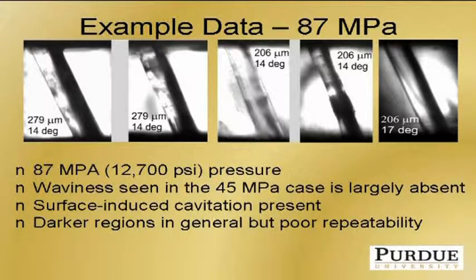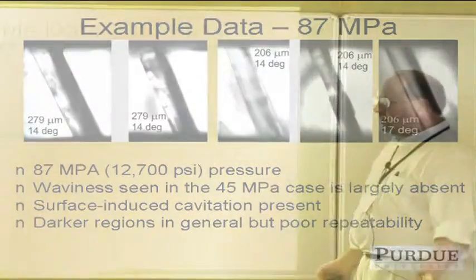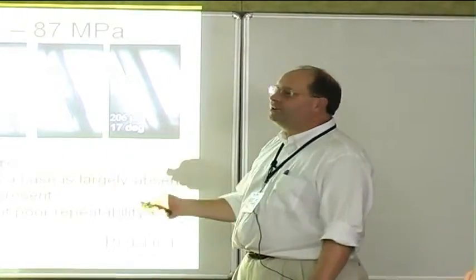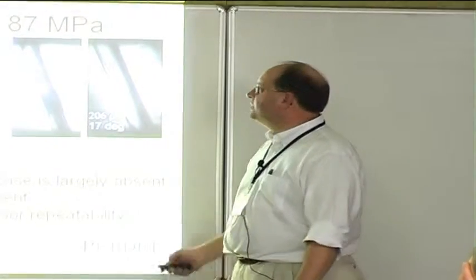There's just so much going on. I don't see how we can try to scale this up, and it's a non-equilibrium process. The bubbles are growing, the bubbles are collapsing on the same time scale as it takes to flow through the orifice. So that's my big push: we've got to go true scale, true pressure, especially if you want to connect up to sprays outside of this.